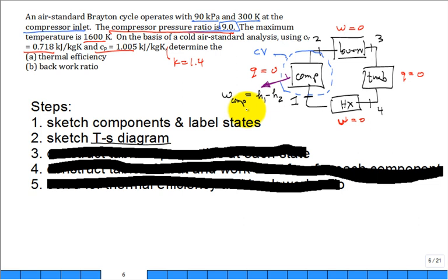Did you have a comment or question? Oh, you were going to answer my question. Thank you. Okay, good. Now let's go over here and do the work of the turbine. That's probably the easy one. The harder one was the compressor. The work of the turbine. Okay, so that would be W turb if you like long subscripts, or WT, whatever. Isn't that H3 minus H4? You're getting very good at the first law for an open system, control volume. Okay. If you need to go slower, go slower. How about this one? We're going to show Q in to the burner, B-U-R-N. All right.